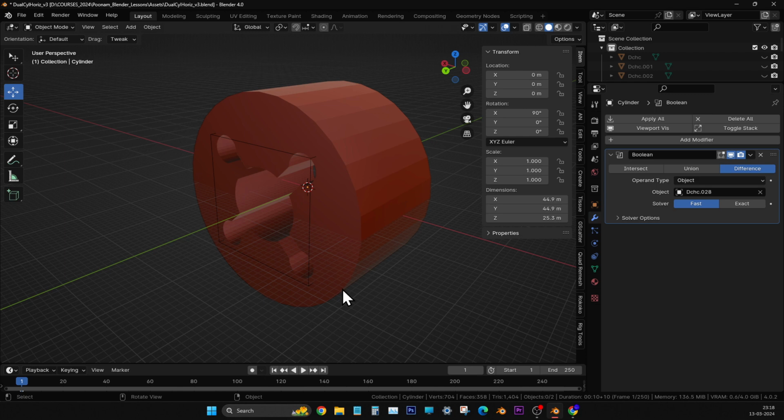Now it is in voxel mode. We have to switch it to smooth mode. Smooth, second. Yeah. Now we have to increase it. This is like making a low-res mesh into a high-res mesh, that option they are giving. So we have to slowly increase it. The octree depth will become very heavy actually. Make it 8 or something, at least 8. Yeah, it will take time.